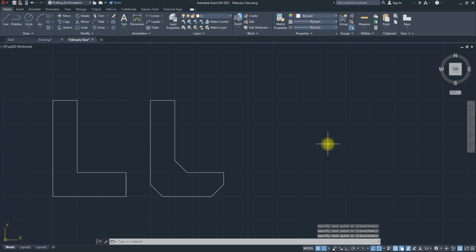Do you see that? So you can actually utilize your snap to create anything you want. You notice that I had to quickly change this for this purpose in the same drawing. So if you have another shape that has a different snap or grid set up entirely, maybe that one has an increment of 5, you can always go back to your snap, change it, and it will not affect this one, if you are only using it to create something. Do you understand? So that's the second way you can use your snap to create objects.